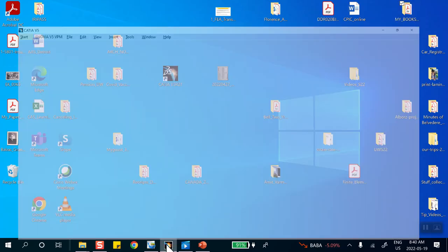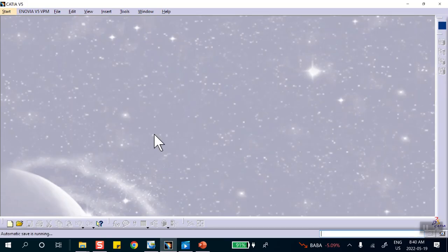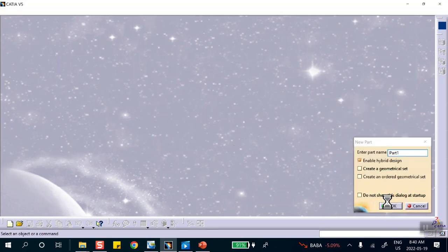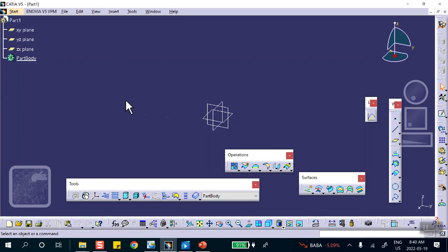Okay, so let's go ahead and make it. I'm not going to worry about dimensions here. Well, I'll use the same dimensions as before, but I'm not overly concerned. I start with a part. Now, there are two ways you can approach beam problems. One is to create the shape, that one line that you draw. You can do it as a sketch, or you can actually go ahead and do it in space. There's a difference between a sketch, where you go to Sketcher and draw something and exit it and do something with it, and drawing it as a wireframe in space.